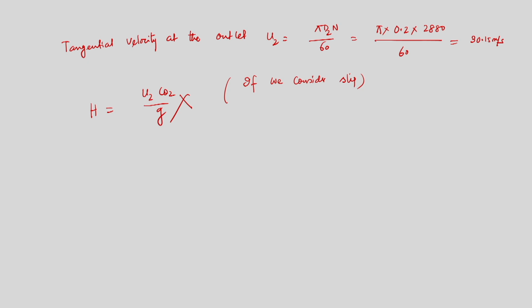In the absence of rotation, the flow direction will match the blade angle closely, but whenever the pump starts rotating, there might be a deviation. So, we need to take the effect of slip into account.